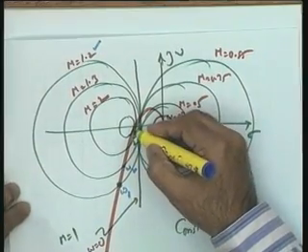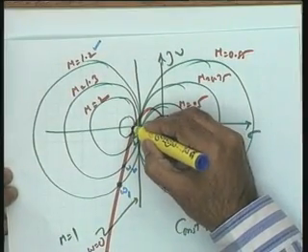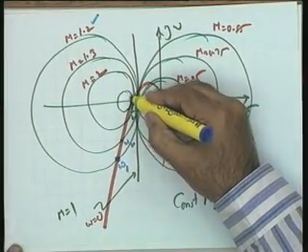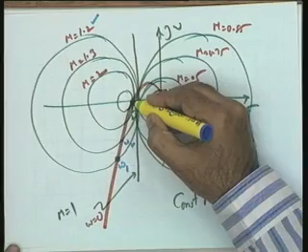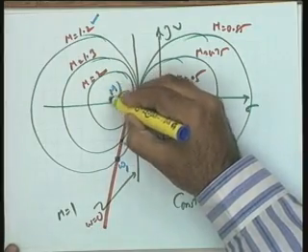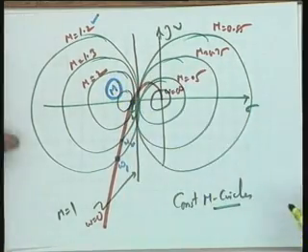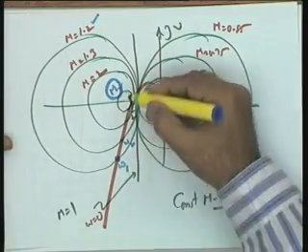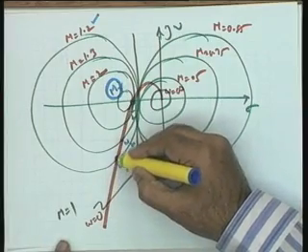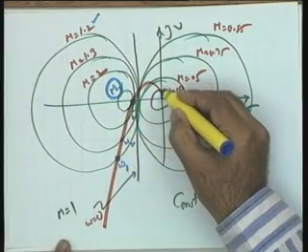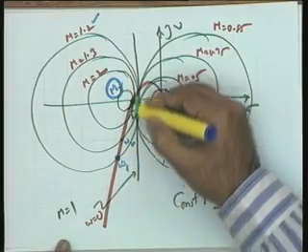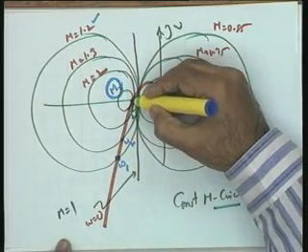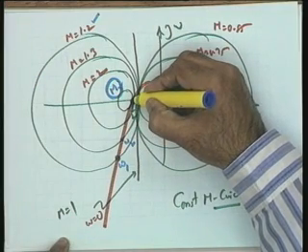So, that way I have the intersections, and you will naturally see this point. I need your attention here, where the plot is tangential to a circle. This is the value of m which gives you the highest value of m. You can call it mr, the resonant m, because as you travel along this Nyquist plot with increasing omega, the magnitude of m is increasing, and at this particular point the magnitude of m is maximum.